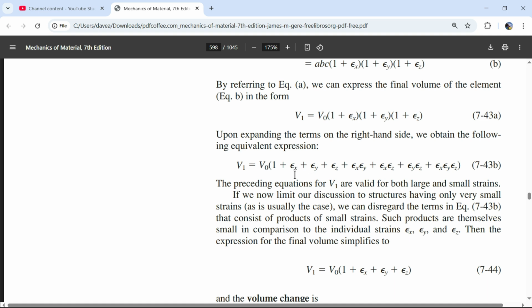And that's a huge strain. 10%? Yeah, 0.1 is a huge strain. Think of strains as percentages. It's the percent change in length. If the original length was 1 meter, and I have a strain of 0.1, I just increased that 10%. Now I'm at a 10 centimeter increase.